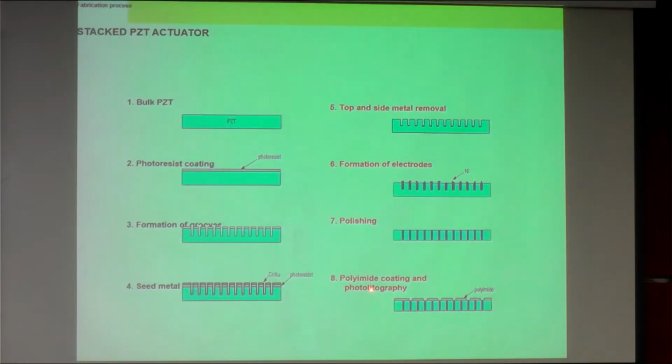Then we get this kind of PZT interlayer between nickel and ceramic PZT. Then we do the patterning on top of this PZT, where you see that on one side you have one open, one covered, meaning we want to have these positive and negative interconnects so that they become the electrode for the actuator.